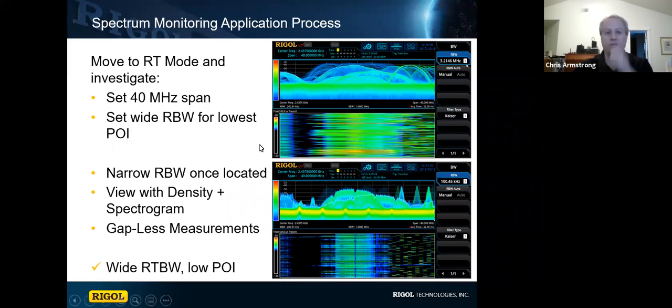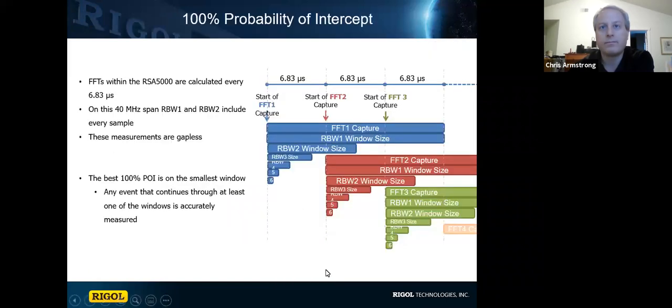If it's all right with you guys, I'll dig into a little bit of the technology here and why that's the case. When we're talking about an instrument like these, the real-time spectrum analyzers from RIGOL, we're pulling in that data all in the time domain with the electronics, capturing it and then converting it with a fast Fourier transform into frequency space, and then posting it up on the display as quickly as possible, giving us a quick, overlapping, very dynamic view.